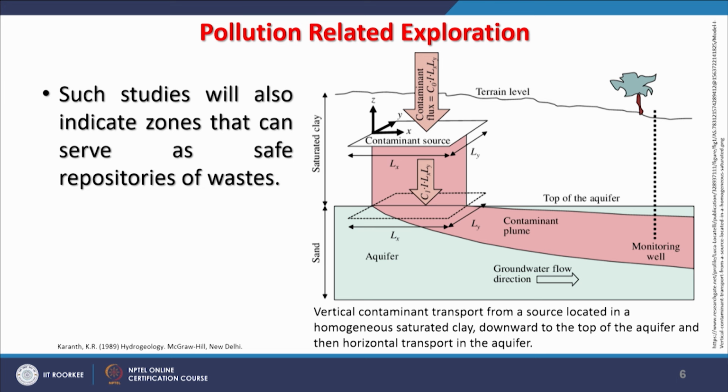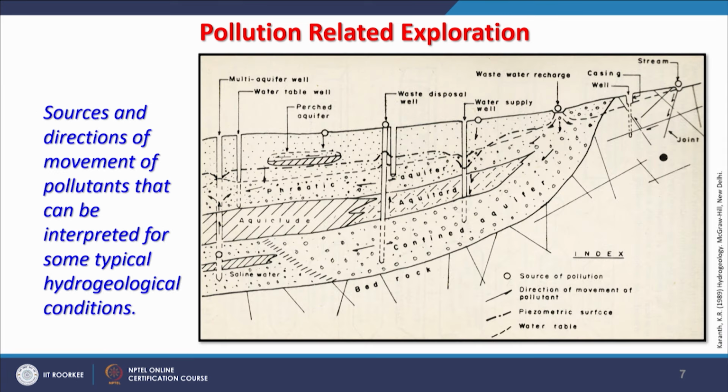Nowadays, before any site is chosen for waste disposal, all kinds of studies have become mandatory, especially the groundwater related ones. First, groundwater related studies, using techniques similar to those for exploration, are performed, and then an appropriate site is chosen, so that no pollutants from the surface enter our groundwater aquifers. Wherever the repositories or disposal sites are, they have to be very safe from the groundwater point of view.